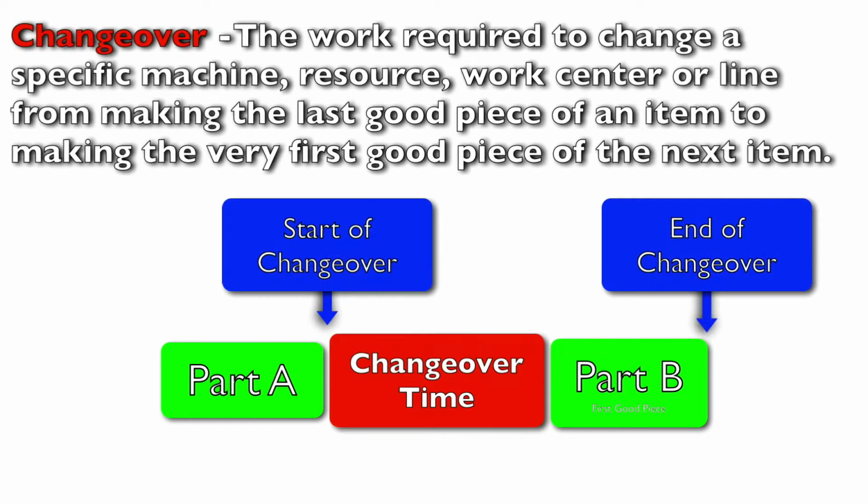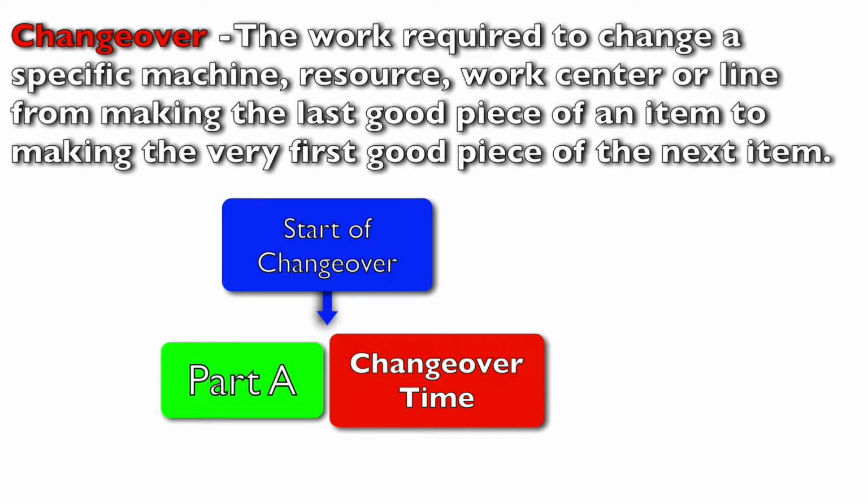Before we start discussing the details of the Reduce methodology, we first need to dig in and understand a few terms that you have been exposed to already. These terms will help you understand the different aspects of your quick changeover and hone in on opportunities much quicker. Let's begin by defining the term changeover. A changeover is the work required to change a specific machine, resource, work center, or line from making the last good piece of an item to making the very first good piece of the next item. So, if the first piece after the changeover is not good, the changeover is not complete.